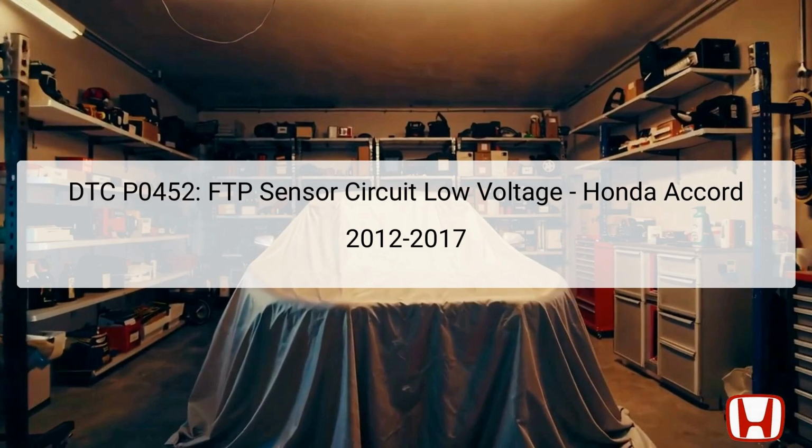Welcome to the diagnostic presentation for the Honda Accord models from 2012 to 2017, focusing on the DTC code P0452, which signifies a low voltage condition in the fuel tank pressure, FTP sensor circuit. Understanding this error is crucial for ensuring the vehicle's performance and emission system functions correctly. The FTP sensor plays a vital role in monitoring the pressure in the fuel tank, which helps in detecting leaks and ensuring proper fuel vapor management.